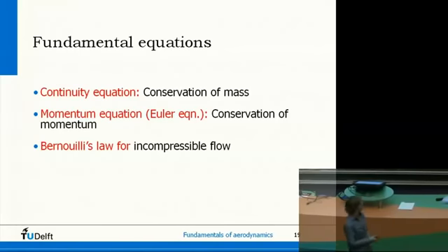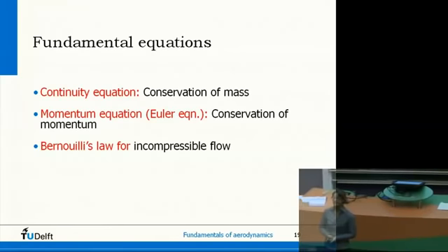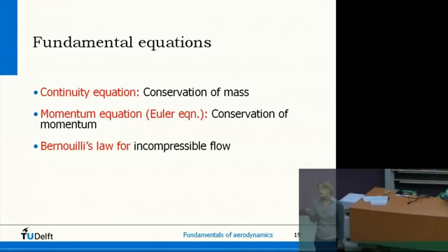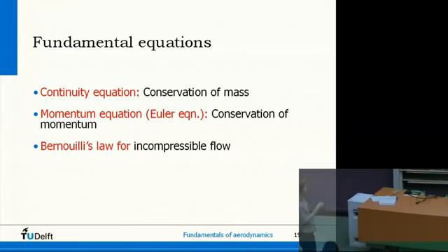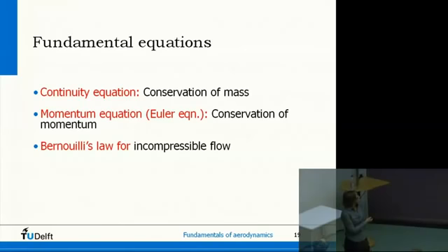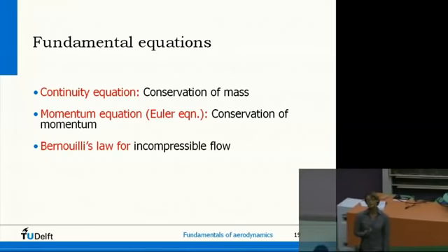If I have time at the end of the second lecture, I can show you, because that is actually my field of research, how this goes about and what you can actually do with it. But for this class, we use simplifying assumptions so we can solve them. So conservation of mass and momentum today, then the energy, which is more relevant for the high-speed flows, I will teach you in the next lecture. The conservation of mass equation is called the continuity equation, and the conservation of momentum, the momentum equation. We have a very simple form of the conservation of momentum for incompressible flows. I will tell you what incompressible flows are, and this is called Bernoulli.